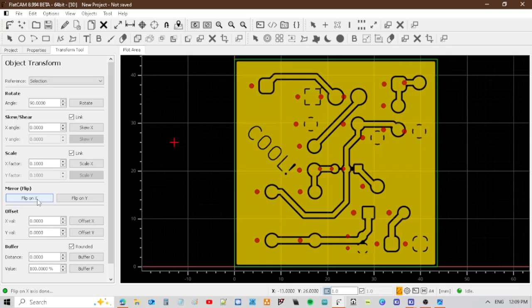If anyone knows how to make this automatically always line up without me having to offset it, that would be awesome. But if you do this, you can just offset these holes. Let's go to like 0.05. Oops, 0.05. So I just kind of get them in the right spot.